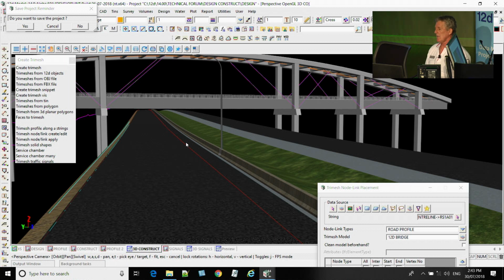It's not a bad little result to see if something's going to work. I also thought about if you did the bridge. It doesn't have to be a complicated bridge like that, but it can still be a bridge. And then you can use the clearance mesh for vehicles and things like that, so you get a good idea without doing much work. You've only really done a couple of center lines, a few points, and just drawn a few general profiles, and you're able to get the road.